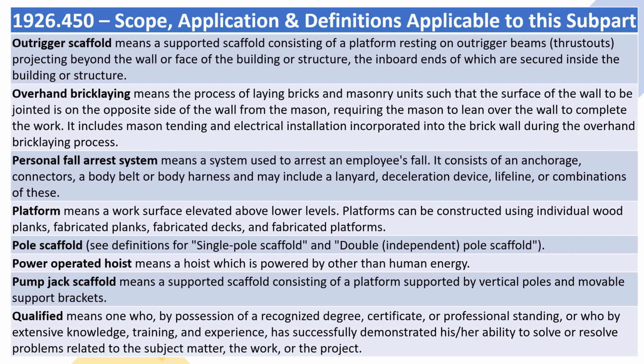Overhand bricklaying means the process of laying bricks in masonry units such that the surface of the wall to be jointed is on the opposite side of the wall from the mason, requiring the mason to lean over the wall to complete the work. It includes mason tending and electrical installation incorporated into the brick wall during the overhand bricklaying process. Personal fall arrest system means a system used to arrest an employee's fall. It consists of an anchorage, connectors, a body belt or body harness and may include a lanyard, deceleration device, lifeline, or combinations of these.